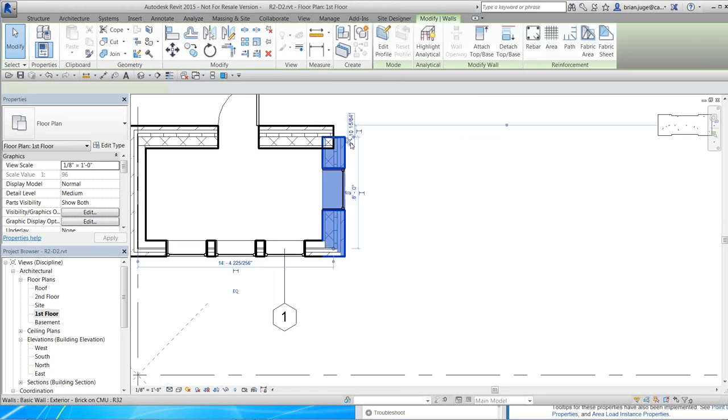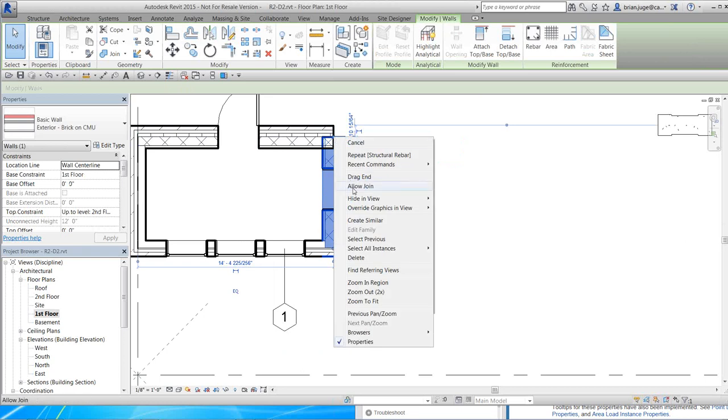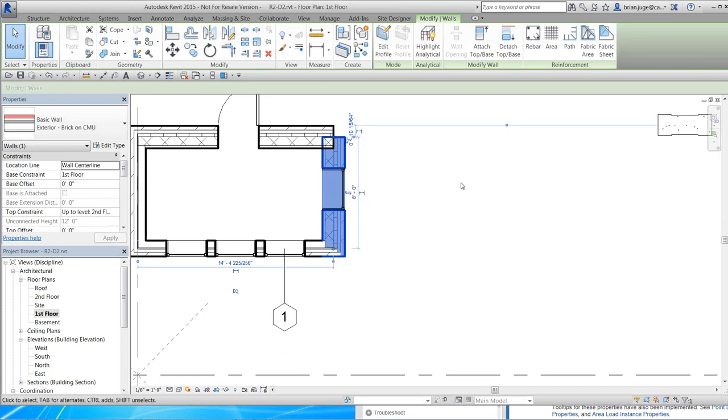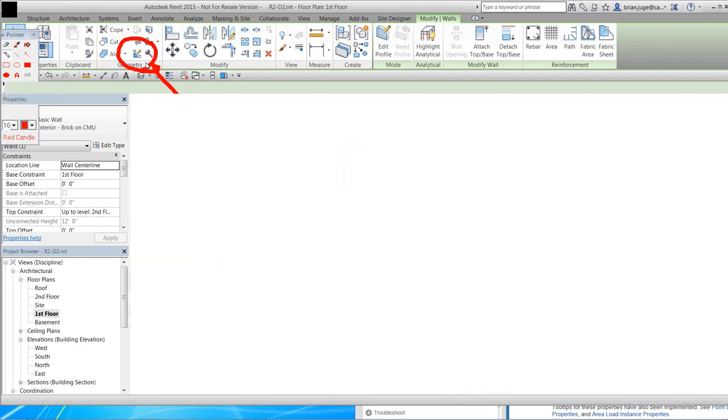Now in the past, anytime you wanted to disallow a joint or allow the joint, we had to come in here and right-click on the dot and say allow or disallow. Well, now what they've done is we come over here to your wall cleanups, and if you've never used wall cleanups before, I highly recommend you've got to get these down. You've got to learn them. They're great tools to have, especially if you're doing more complex foundation site work. I find they're really nice things to have, especially tying those site walls into the existing foundations of your house. It's been great for me.